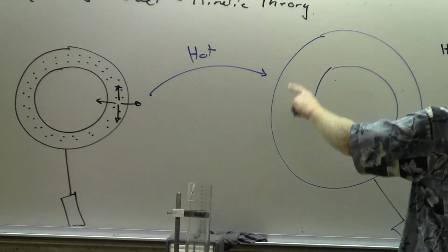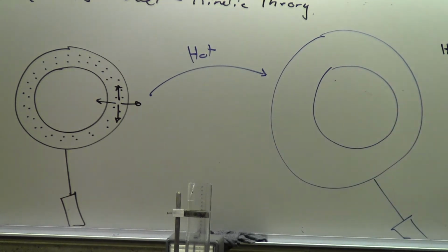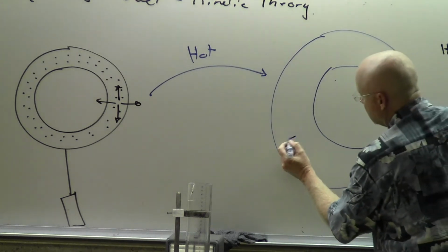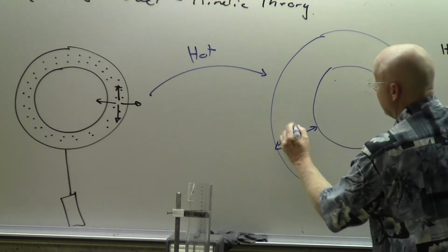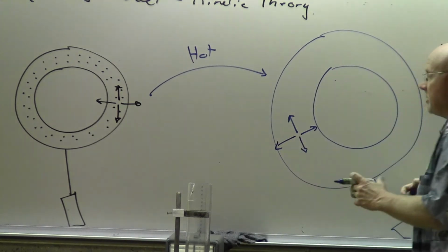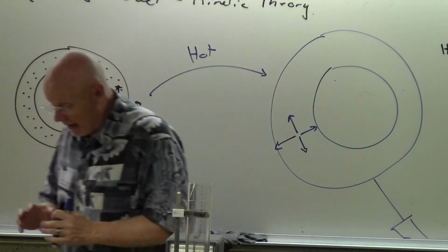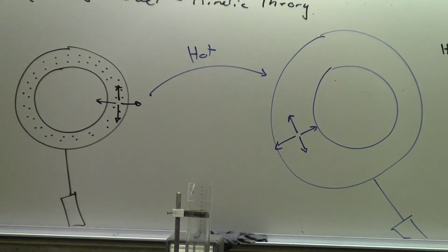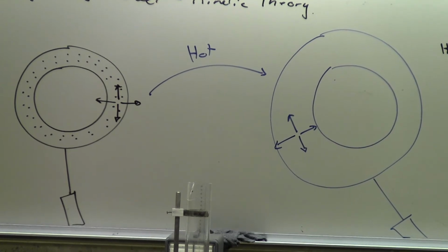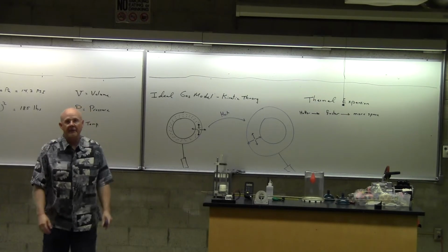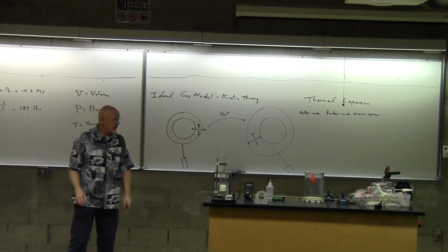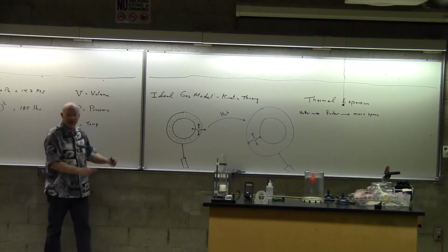And it's the circumference that makes the size of the inner hole. And so does the width of it increase? Yes. But also at the same time its circumference does. And so as I said, maybe a little bit of a surprise, thermal expansion means, because the circumference gets bigger, that the hole in a ring gets bigger when you warm it up. And that's a little bit tricky, I think, to see, and hopefully this helped.